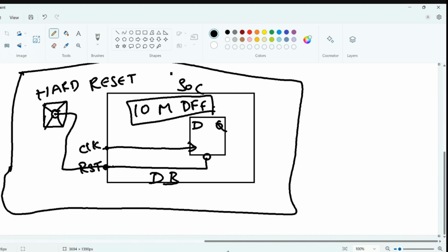Even if the clock is coming from a port, it is not synchronous. You need to synchronize the clock. You don't know how the clock is coming. So that is the reason we always have internal PLLs, so we know the exact width of the clock and the frequency of the clock, 1.2 gigahertz or whatever. You will get a proper, free running clock. Now the reset is not stable, so we use reset synchronizers, double reset synchronizers.